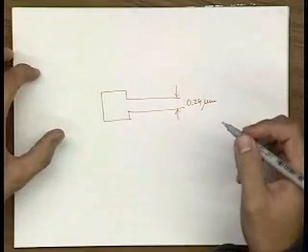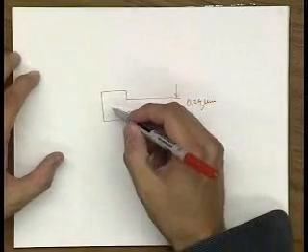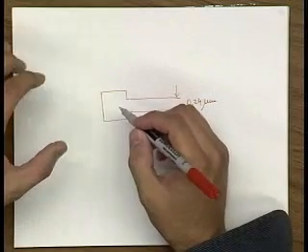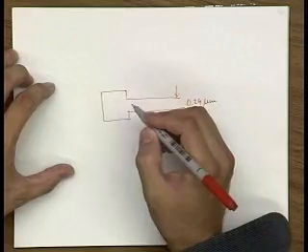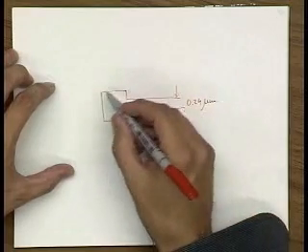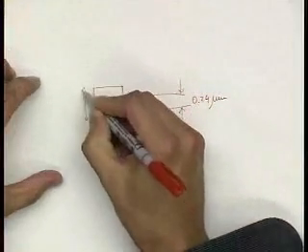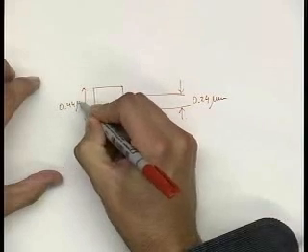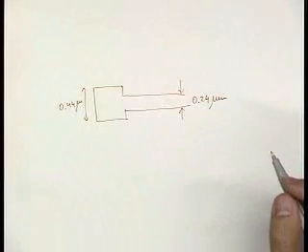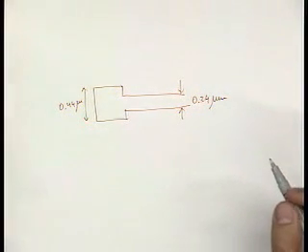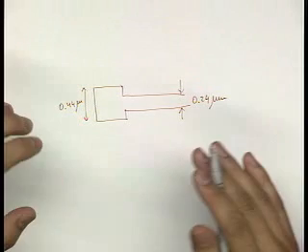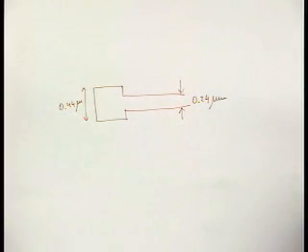So in order to create a good contact, you have to have some enclosure over that via hole. And then you have a rule for that as well that translates into minimum size contact in this technology to be 0.44 micron. So be aware that the contact is basically bigger than your minimum size transistor. So for that reason, you really need to use contacts carefully and try to do everything in one metal layer as much as you can before you escape to higher metal layers.